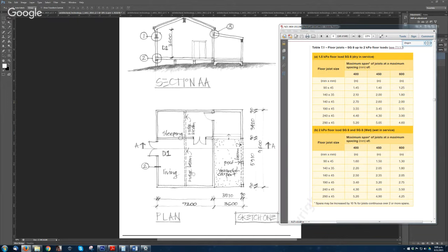Does everyone know how the joists and the bearers and the piles all sit and what it actually looks like? If you know that, then you can easily figure out, or at least visualize, the loaded dimension. Because if you don't really know how it looks, it's hard to figure out the loaded dimension without visualizing the shape of it as if it was a real building. Like the bearers, they're running along this way.